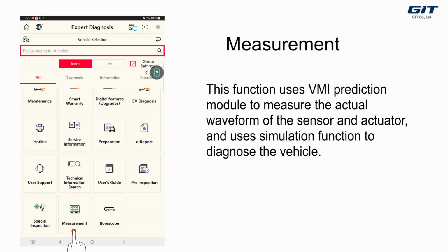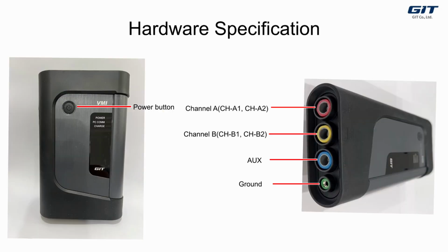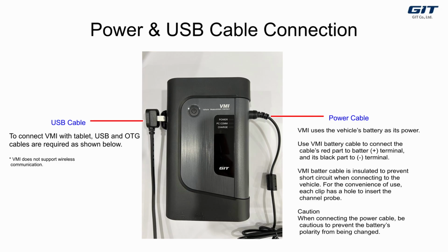This function uses the VMI prediction module to measure the actual waveform of the sensor and actuator, and uses the simulation function to diagnose the vehicle. To connect VMI with a tablet, USB and OTG cables are required as shown below. VMI uses the vehicle's battery as its power.